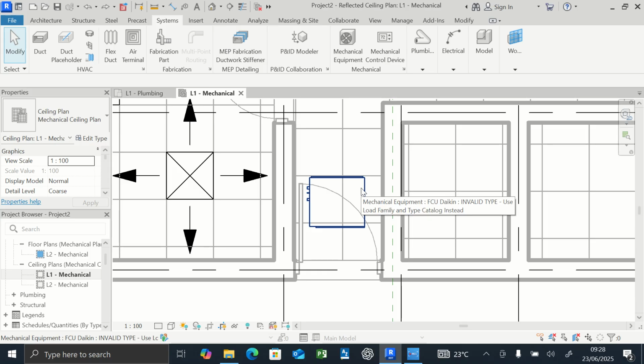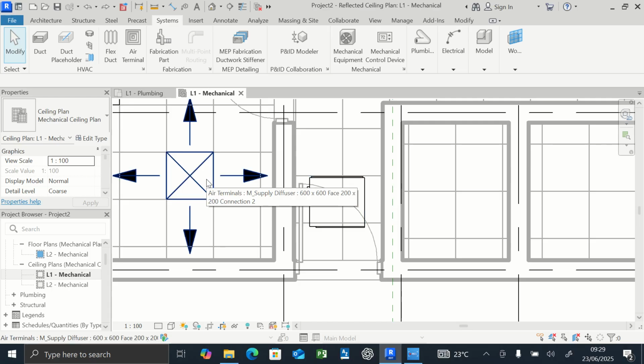In continuation of the HVAC system we began to add to the office model in the previous tutorial, today we are going to be creating ducts that connect the ceiling concealed unit, otherwise the fan coil unit, to the air terminals, right? So here is our unit. That is the ceiling concealed unit. Like I mentioned before, this is slightly above the ceiling, and we have our air terminals flush with the ceiling to create allowance for ducts to connect to them.